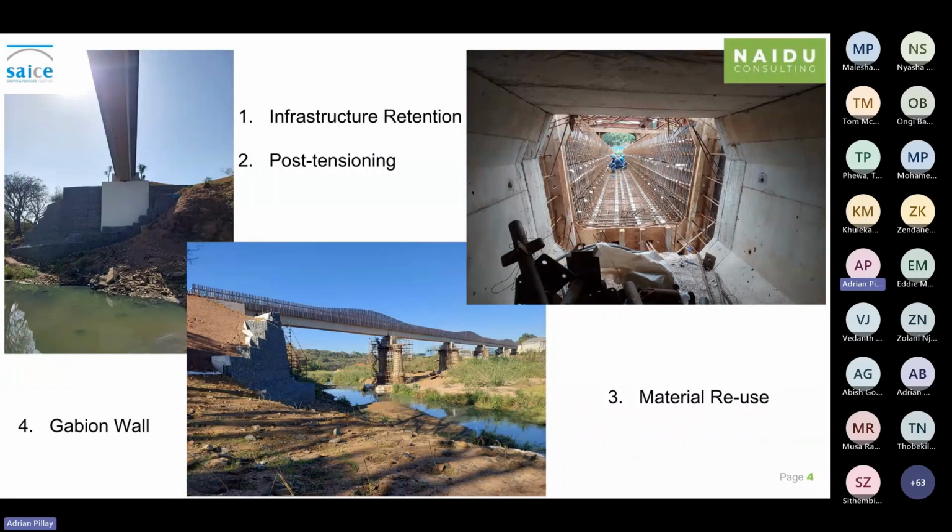In using the post-tension beam, which was cast within the existing steel truss option for the bridge deck, staging for the bridge deck over the river floodplain was completely eliminated, in addition to the ease and speed of construction. The deck slab was made continuous over the piers to eliminate the necessity for expansion joints, limiting them to the abutments only. A notable aspect of this project was the procurement phase, which occurred during the COVID-19 pandemic period.